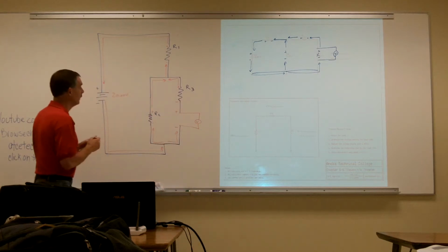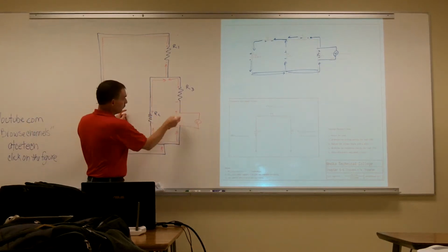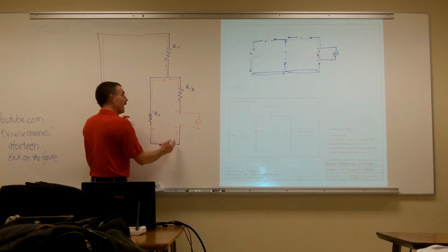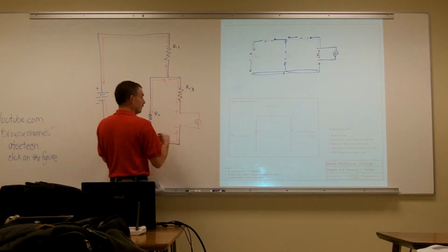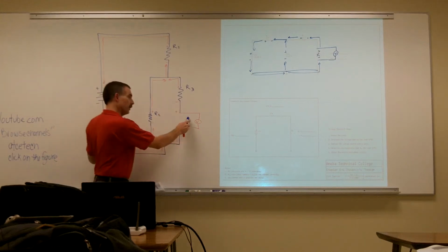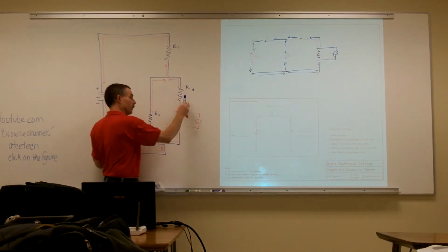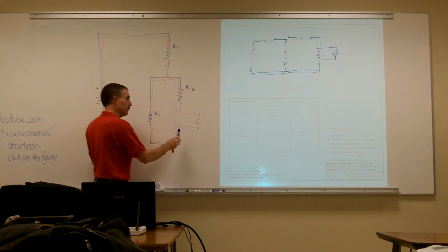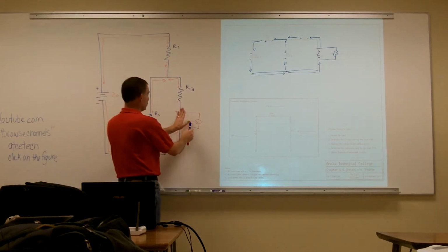Okay. So now with our RL out of my circuit, would I have any current going through this branch? No. I have it open, so there's no current path other than when I hooked up my voltmeter. Now I have a little bit of current going through there, but that's immeasurable. We don't have to worry about that. We can just consider that as an open.